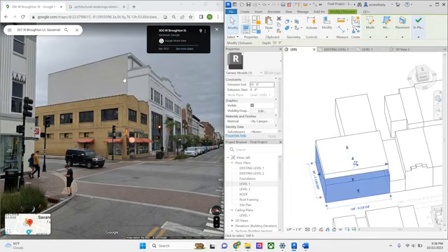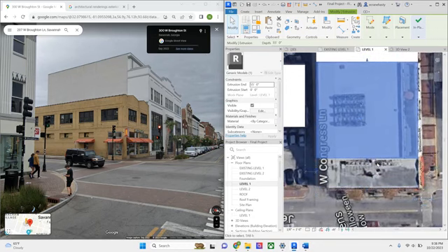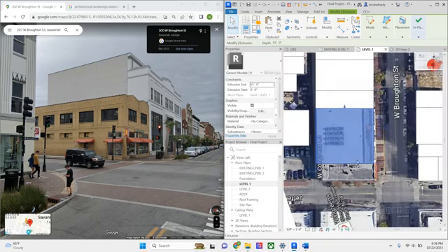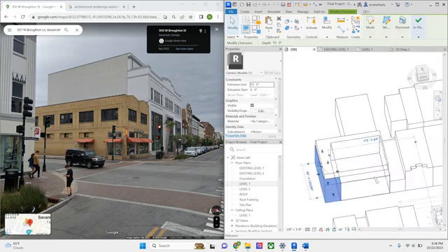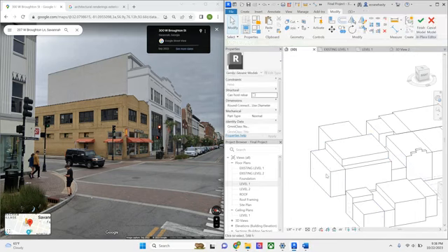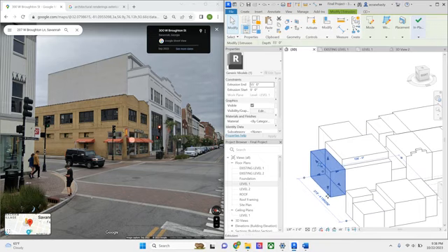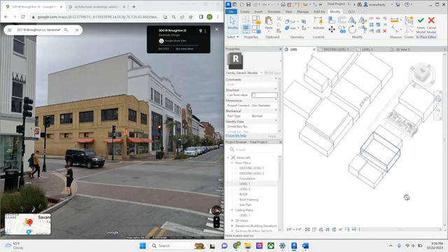See what I mean? So see, here's that chunk, but then there's another building here that I missed. So I'll just go back and I'll find that spot. Probably mirror that over and just stick it there. We'll take that. That belongs on top of that building. This is lower than this. It's probably the same height as that, so I'm just going to bring it down to 40 feet. And we're starting to get a little building context there.